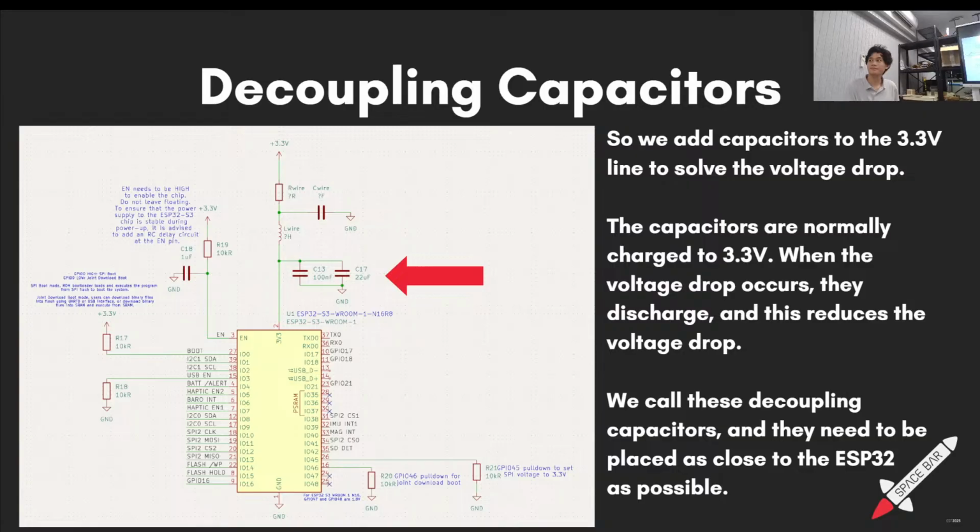Is the resistance constant throughout the whole thing? As in this entire ideal trace, yes. So we modeled it as a single series resistor, but in reality, the resistance is spread throughout the entire trace. Same for the capacitance. The inductor pushes back, which lowers the voltage, which makes the capacitor need to fill in. Exactly, yes.